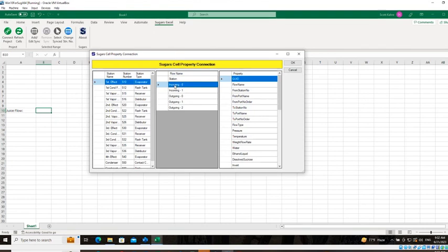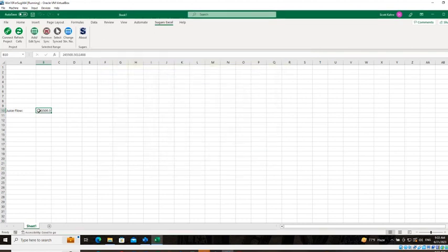So right here, if I click this, now I get a list of parameters associated with that flow. So I think all we really wanted was the weight flow rate. So if I check or select that field, click OK. Now we have the mass flow of that juice that was coming into station 510 input port 0.